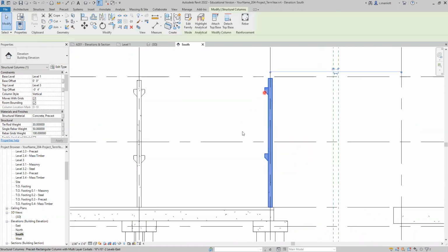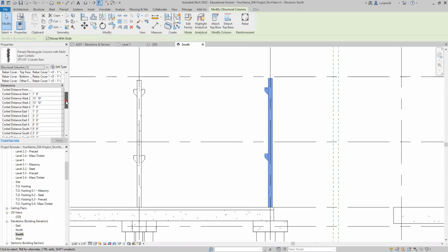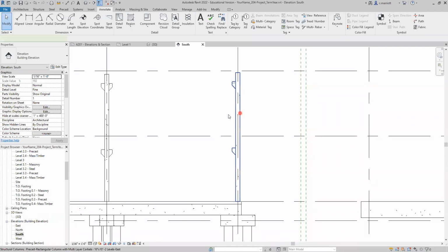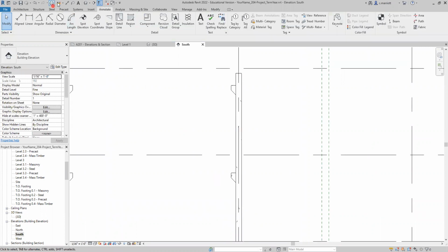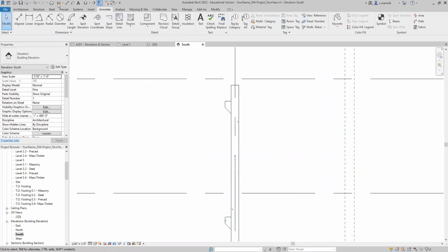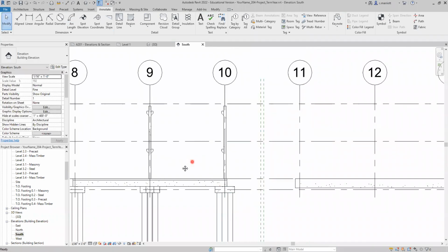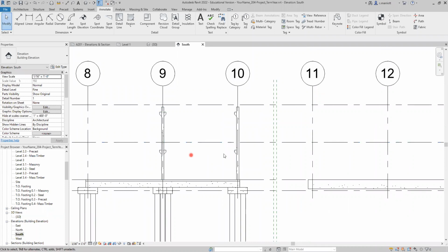I did that incorrectly. Let's take a look at that. It must have made the adjustments automatically. So let's go back down here. Okay, I see what I've done incorrectly. Let's make another little change, same as this one. Instead of -4, this should be -8 and apply. Okay, and let me double check my measurements here. Right click, snap overrides perpendicular, 2 feet 6. And I'll just check this top one too. 1 foot 8. Okay, everything looks good with that one. I want to make sure that they align so our beams have a place to rest.